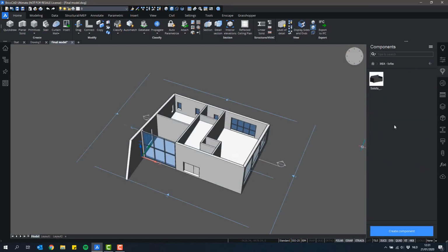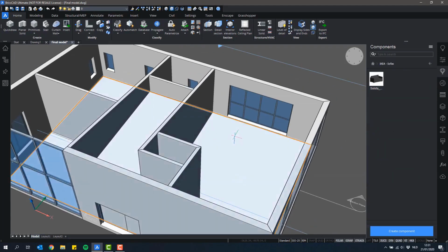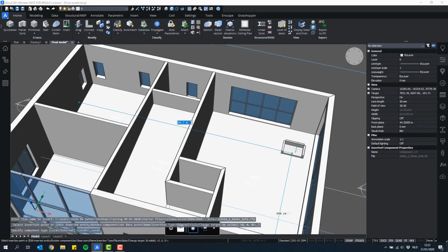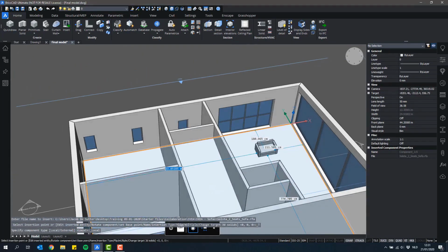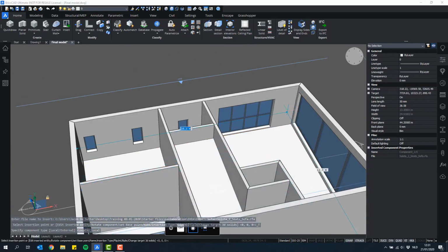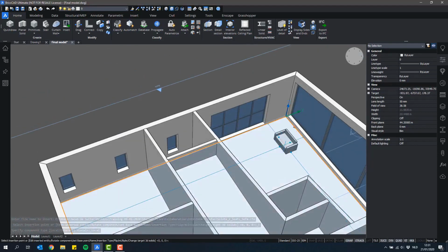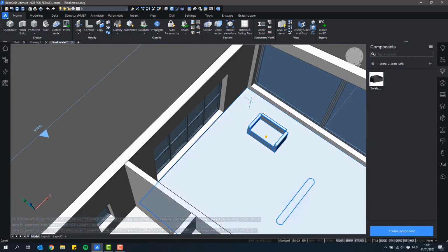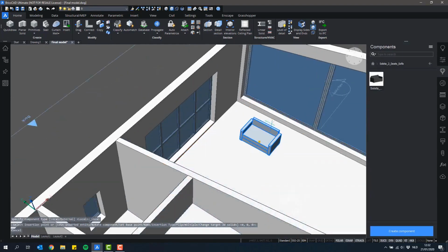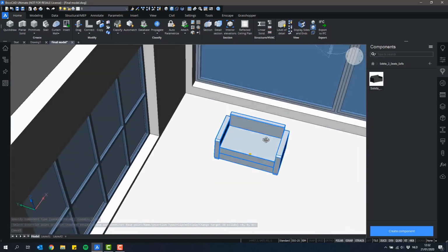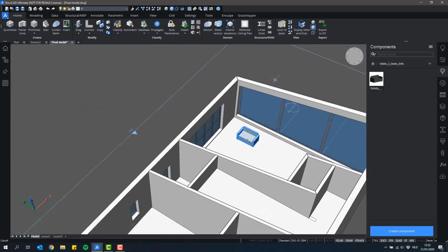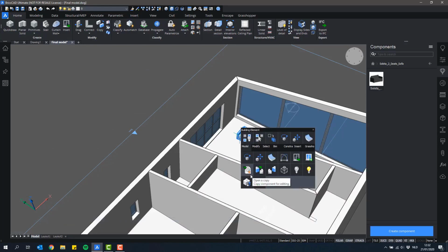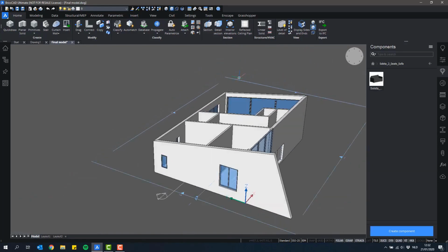Let's say, for instance, here the sofas. There is one sofa. And I can simply drag and drop it into my drawing. And this will be converted to DWG automatically. There it is, okay. But again, I can't change the width or height, for instance, of this sofa, unless I parameterize it myself, which I can do by clicking Open Copy and save it as a new DWG, and then parameterizing it, as we saw in an earlier section of the training.